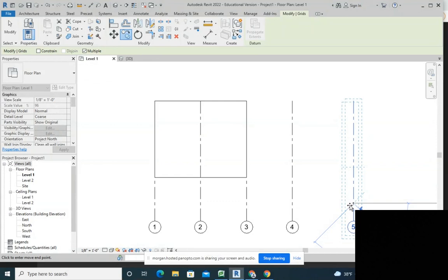Okay, so click it, type in CO, click it again, then come over this way, hover and type in where you want to go, so 15 feet and hit enter. There you go. You got yours, all good.